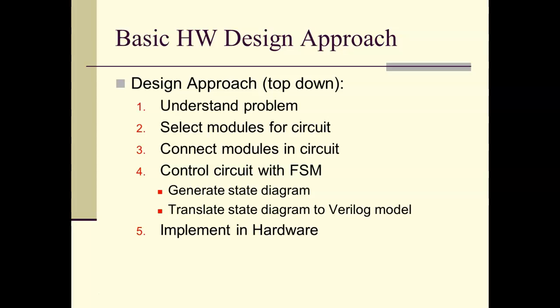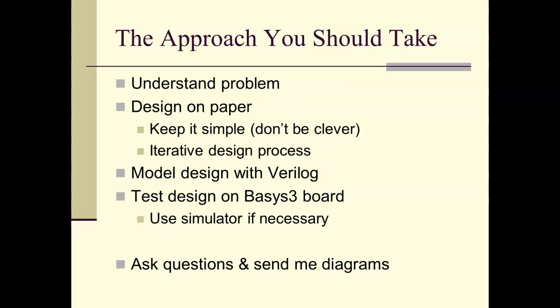Use the modules, interface with the modules, and then drop them down, connect them in your circuit. Next thing you need to do is control that circuit with a state machine. Generally speaking, always start with the state diagram, then translate that state diagram to Verilog. And lastly, just implement your experiment in hardware, which for us is FPGA and your friendly Vivado.